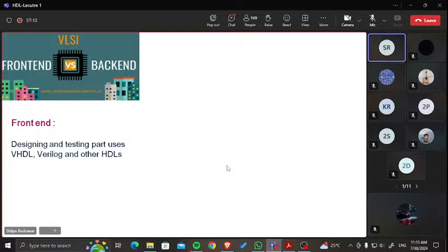VCC or ground. But now in a design, are you able to give hard input? Are you able to give VCC and ground? No. So what do I have to give? I need to give soft input over there. Stimulus, vector, these are all names for the same thing. Stimulus is soft input, okay? I need to generate that. I have to give to A and B, so I need to generate 0 0, 0 1, 1 0, 1 1. What generates that is called a test bench.